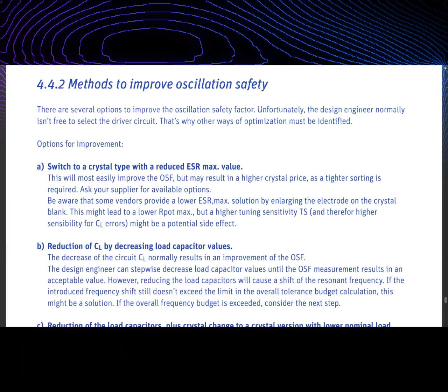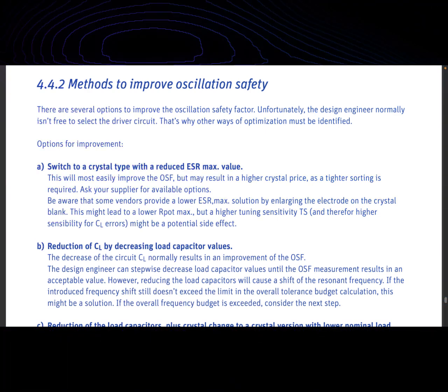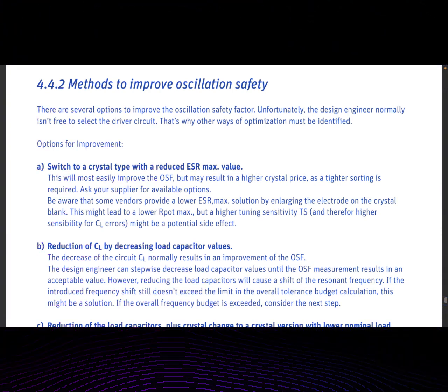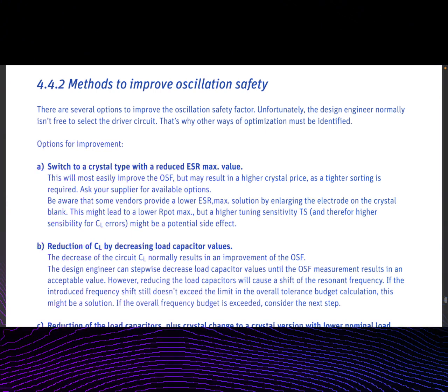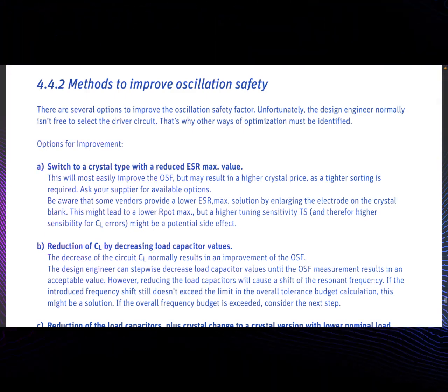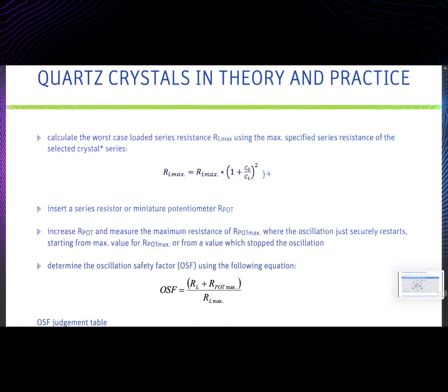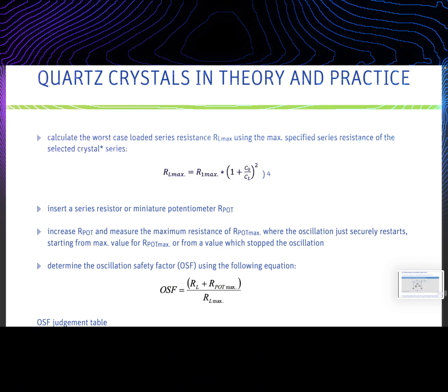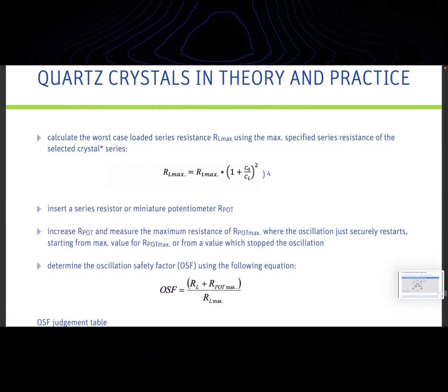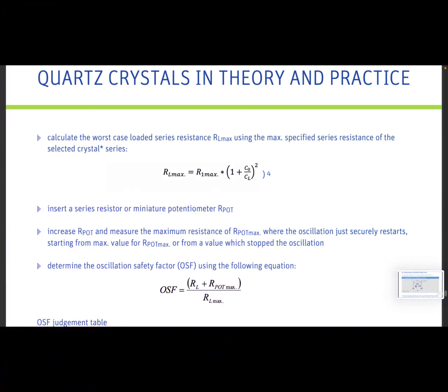Low long-term frequency drift. The long-term drift of the resonant frequency of a crystal is called aging. The aging of a crystal resonator is related to the stability of its mechanical components and to a well-controlled manufacturing process. Resulting from that, mid and long-term stability manifests in frequency drifts of only a few parts per million per year at room temperature.